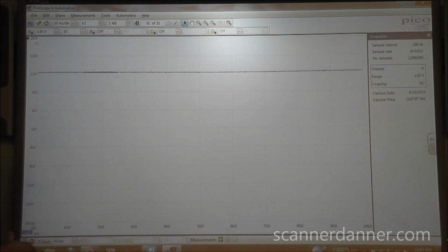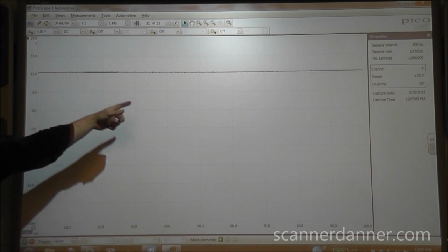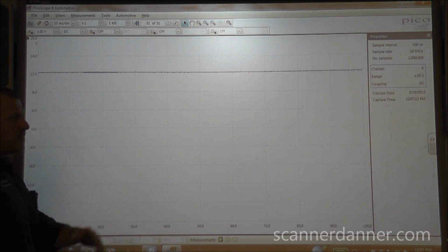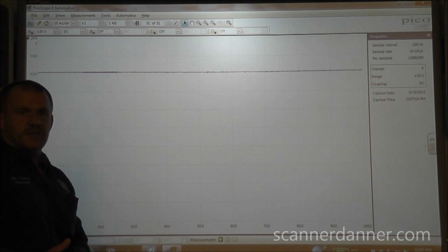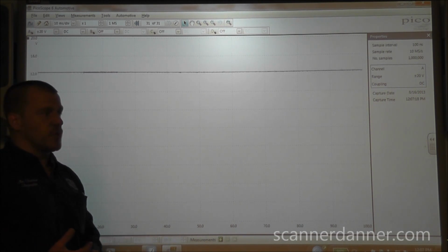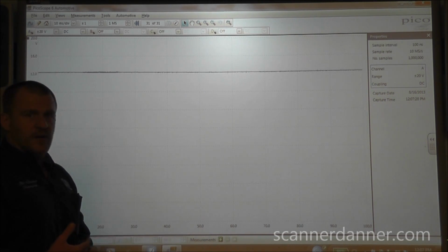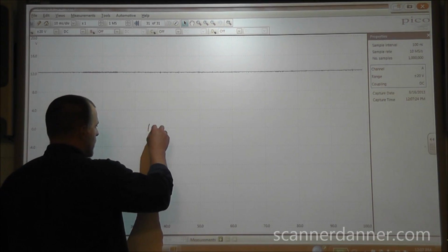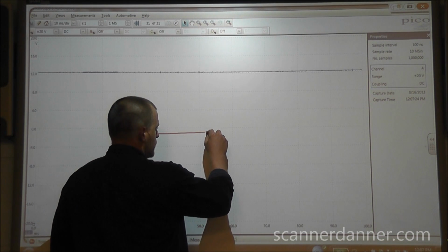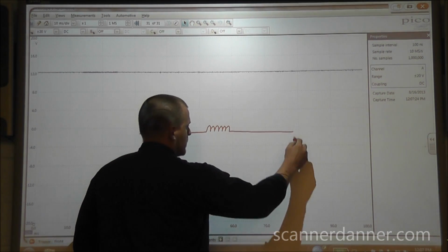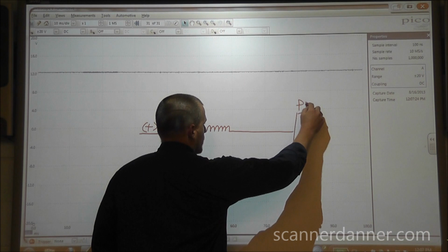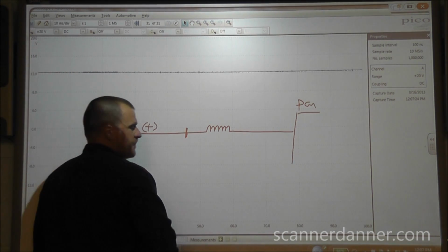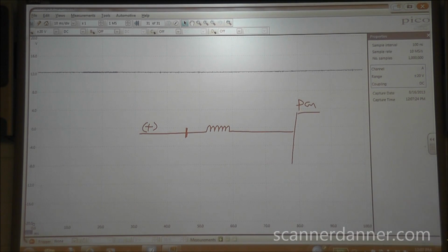And what I want to do with you guys is not look at voltage, I want to look at current. And I think the one that I want to use is the low amp probe connected to an ignition coil. And I'll get you a shot over there in a second on what that looks like. But basically what we're going to do is take the positive lead that goes to the coil primary, this going to my engine computer, and I'm going to put an amp clamp, an inductive amp clamp, which looks like this.